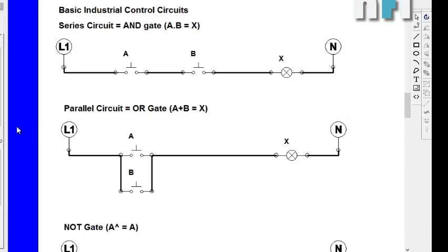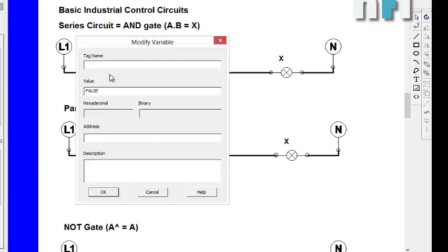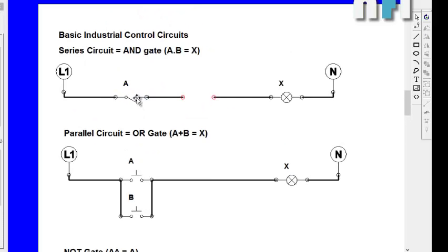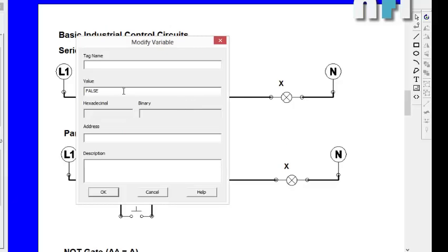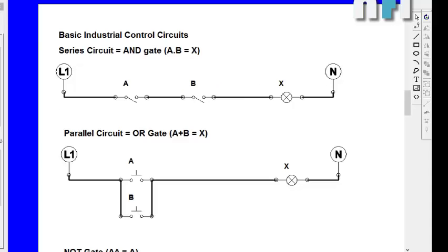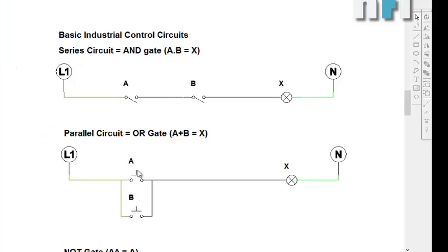So the next thing we are going to do is the latching, but before latching I just want to share that we also have a toggle switch. These toggle switches typically do not have a spring. They maintain their position once they are actuated. They are generally used in household actuation. Bell switches are typically push buttons, but when you turn off a light in your room, that is a toggle switch. When you press this button it will remain here, and when you press this one, this will turn on. There is no spring here, otherwise it's again normally open, similar to this one but without a spring. They retain this position.